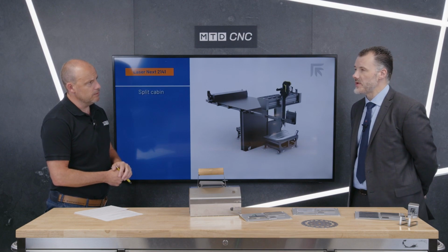Surface finish, generally speaking, with a CO2 laser on a thick material, you would probably get slightly better cut quality. With a fibre laser, you'll get really good cut quality and a very fast speed on a thinner material. As I say, the lines between those two now are getting a little bit more greyed because the technology is advancing. It's moving on so quickly, isn't it?